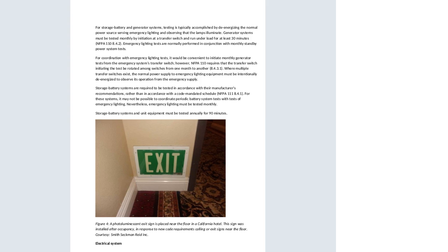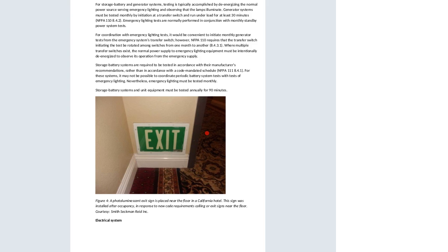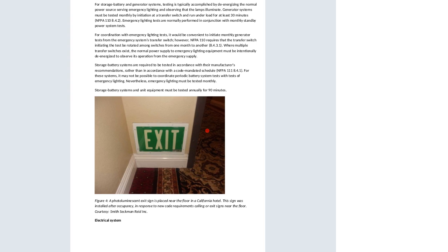The generator systems must be tested monthly by initiation at a transfer switch and run under load for at least 30 minutes. Emergency lighting tests are normally performed in conjunction with monthly standby power system tests. It would be convenient to initiate monthly generator tests from the emergency system transfer switch.